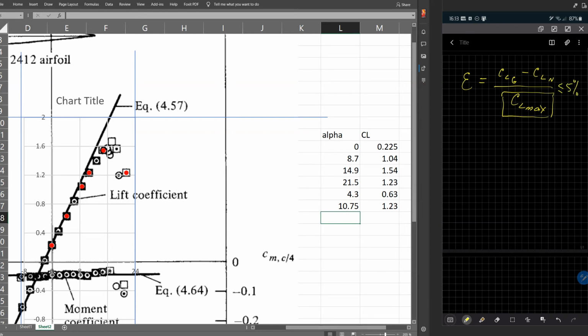You make this kind of estimation and you will easily obtain the error of your calculation. Why is it important to know the error of digitalization? It's important because then you will make a numerical simulation and you will also obtain a difference between the numerical results by Fluent and this data you took from graphics.